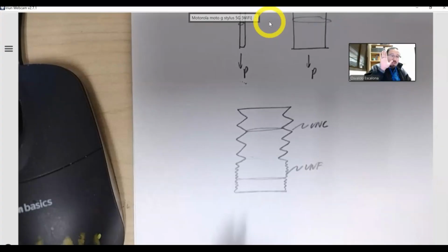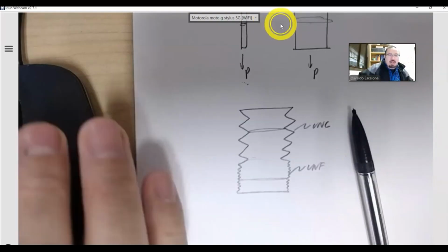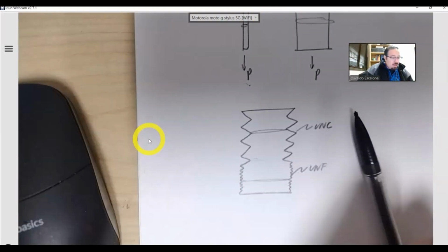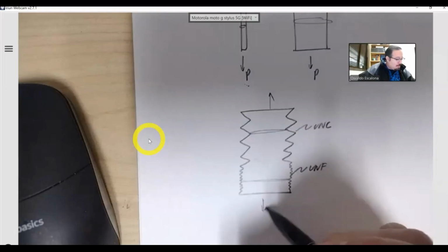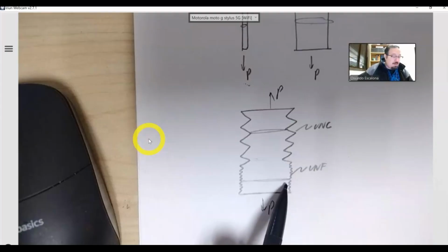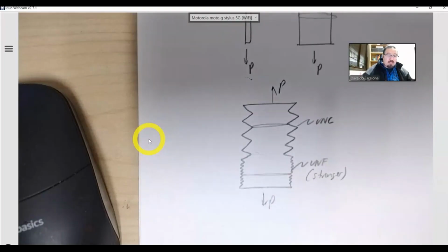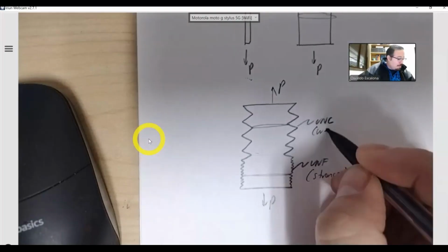It's kind of like when you apply a load, like if you were to poke yourself with a needle or with your pencil, it would be ouch. You're being stressed by the amount of force on that small area. Now, if I were to apply the same force, but instead of applying it on a little point, I were to distribute the load, I would not feel the same punch. The same concept happens to the material. When I apply the load, the one that has the most area will have the least stress. Therefore, this one will be stronger and able to restrain more stress. This one will be a little bit weaker.